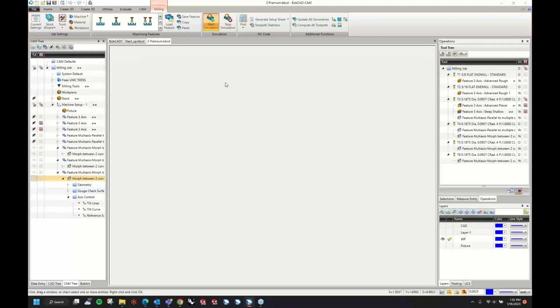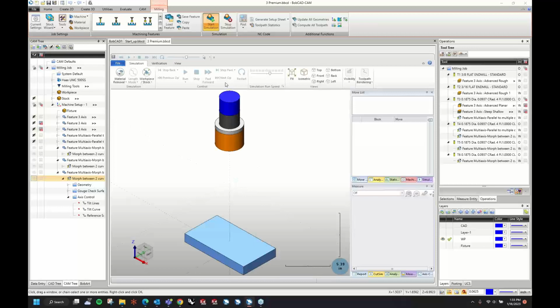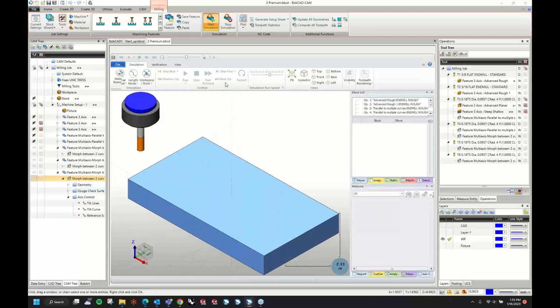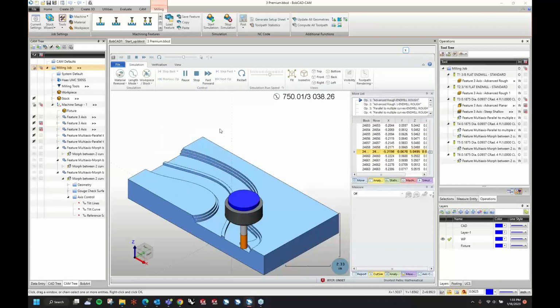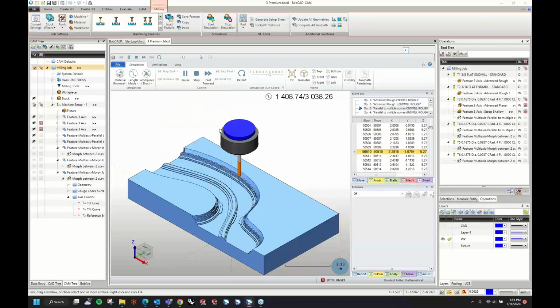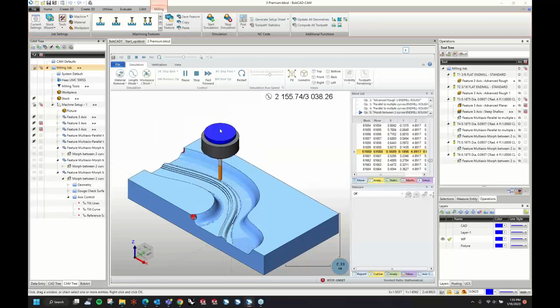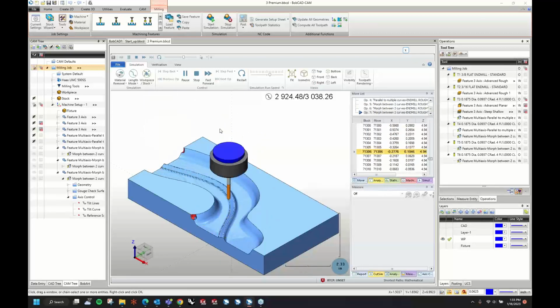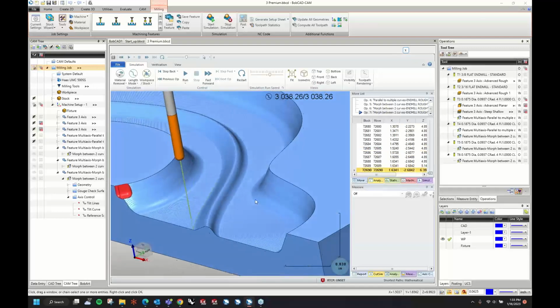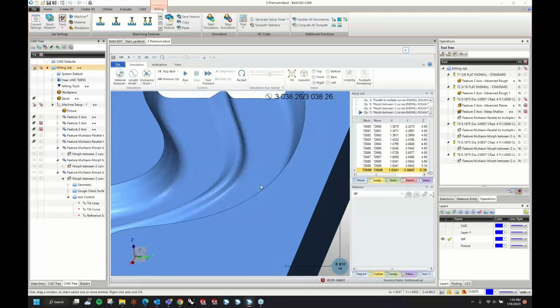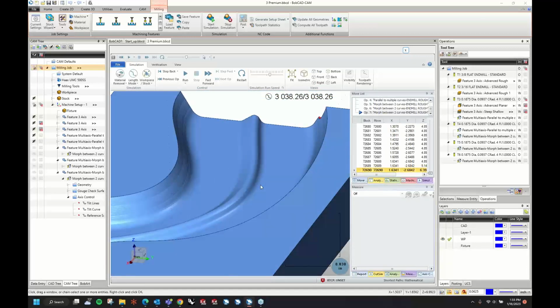But another couple of great things about these multi-axis is you can do other things like extend your toolpath out without having to modify geometry. You can use 2D containments if you need, but they're really not necessary because you're using surfaces. You do have a lot more flexibility with them. There's a lot more power behind it. Yeah, I need to change those retracts. It's going to look like it's crashing all the time. But you can see I'm getting a much better finish now with all of those toolpaths rather than doing the planar and Z level or trying to manipulate those to make this all work.